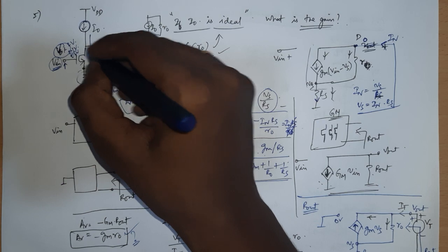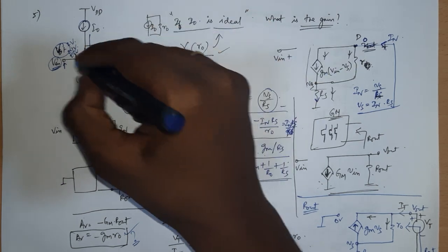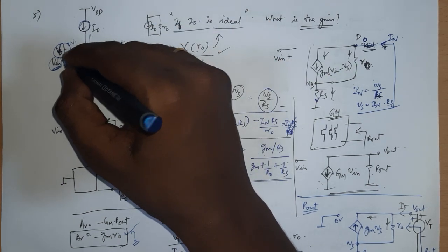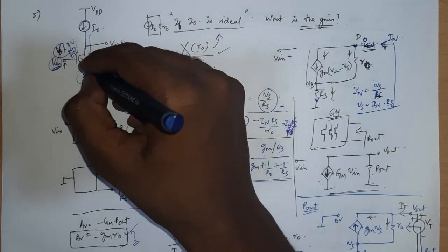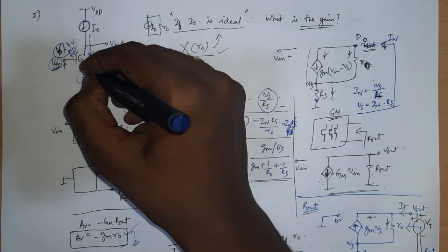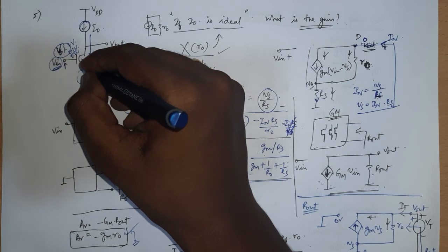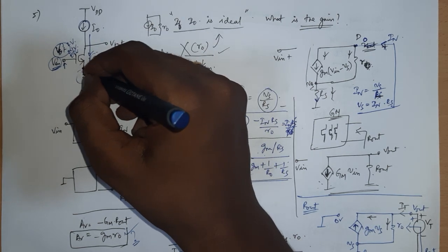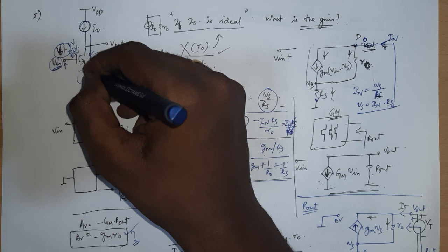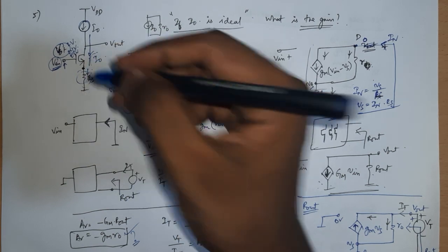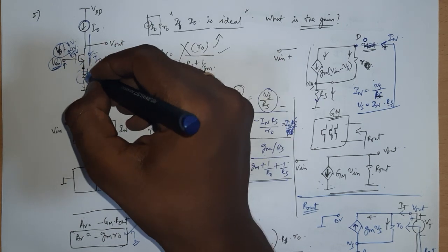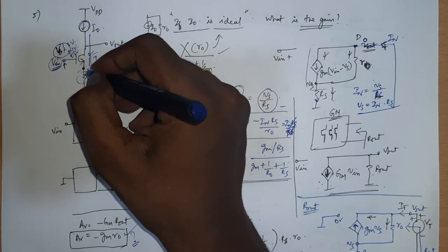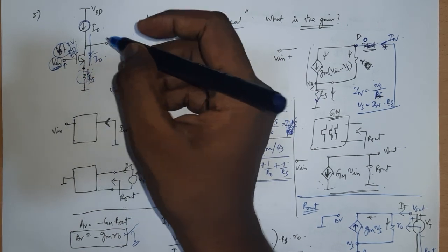If I do 2.2 volt, then also the current through the resistor is I0, meaning for whatever change I do at the input side, this current through the resistor is not going to change. It doesn't respond to the increments. It's like saying the ground is actually here. There is no additional current flowing into this Rs in the incremental picture than what it was flowing in the DC picture. So as far as the incremental picture is concerned, this Rs need not be there at all.